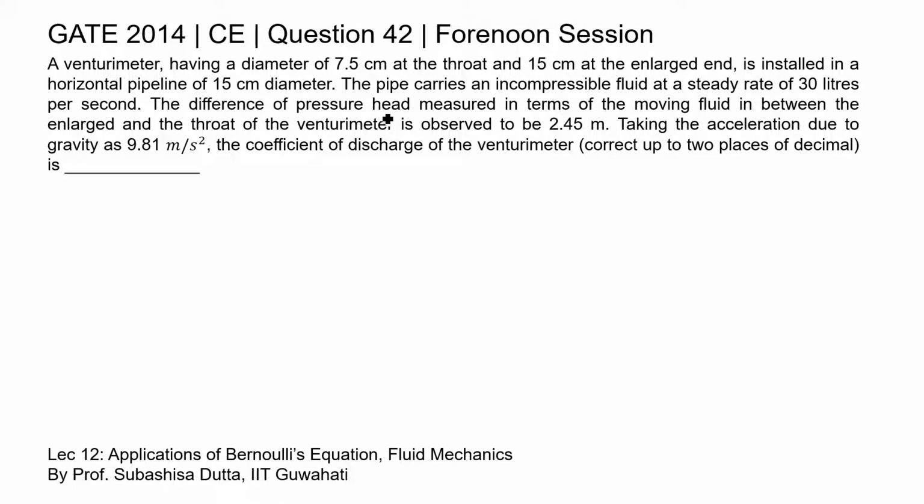The difference of pressure head measured in terms of the moving fluid in between the enlarged end and the throat of the venturi meter is observed to be 2.45 meter. Taking the acceleration due to gravity as 9.81 meter per second square, the coefficient of discharge of the venturi meter is. So, in this question a venturi meter is given.